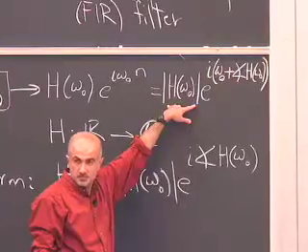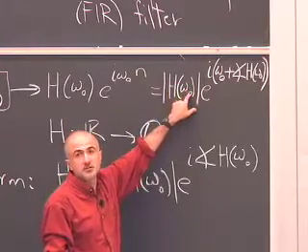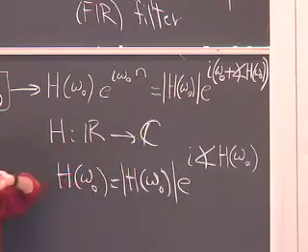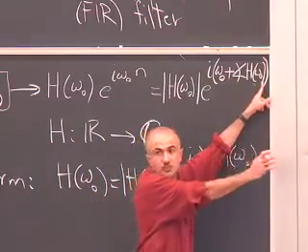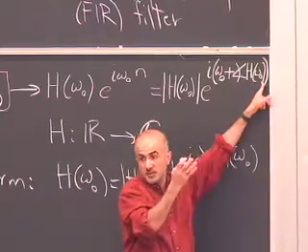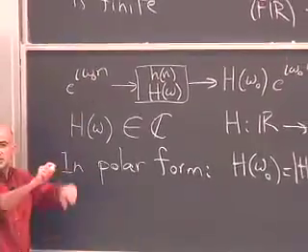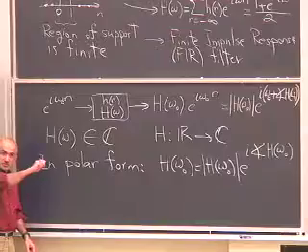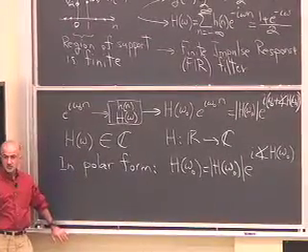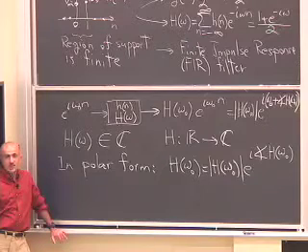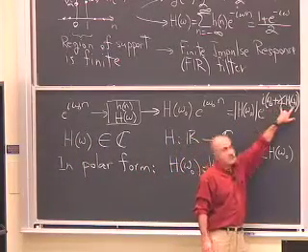This is the amplification, how much the filter favors this particular frequency. For some omega naught, this value will be small. For some omega naught, this value will be large. For other values, it'll be in some intermediate range. And the phase of the filter tells you how much this sinusoid moves back and forth to the left or to the right. Now, the effect becomes very complicated when you have a signal that consists not only of this frequency, but other frequencies. You saw an example of an audio signal where I shifted the slide bar. And you saw how just changing the relative phase of one sinusoid with respect to the others mangled the overall sum of the signals. So the effect of the phase is not very easy to see. And in fact, it's so complicated that there are some filters whose magnitude response is constant.